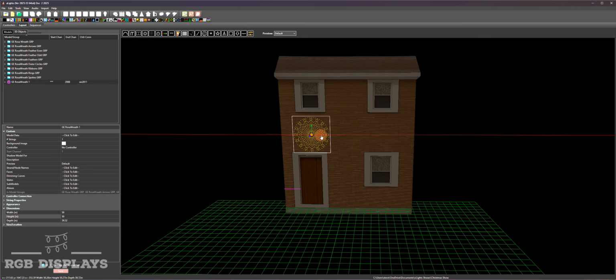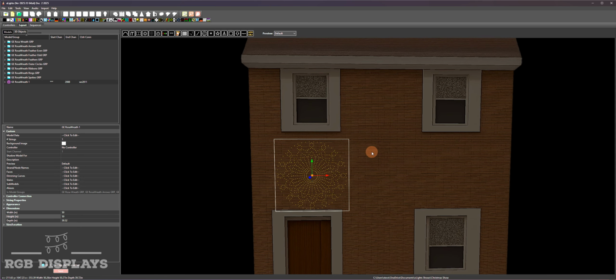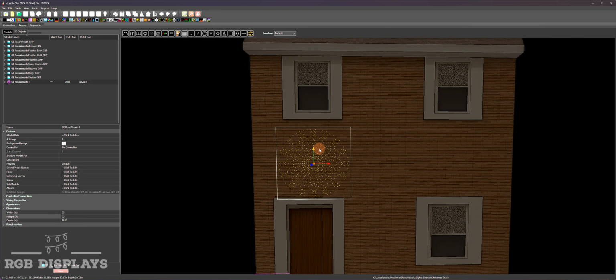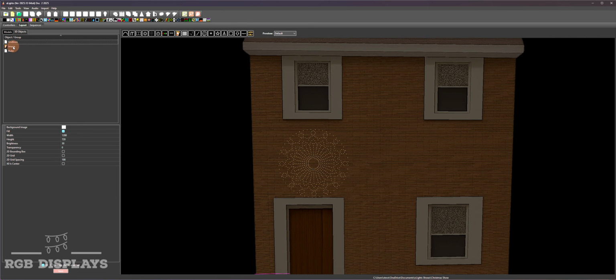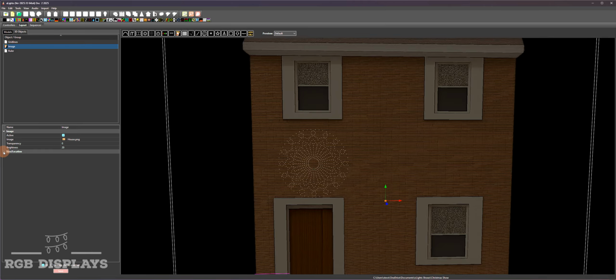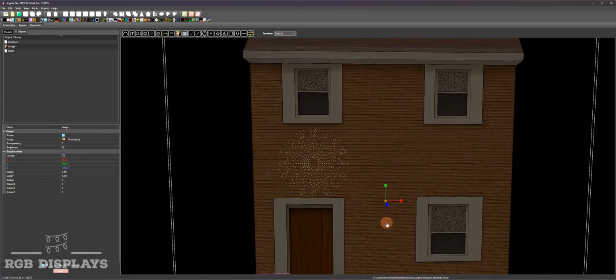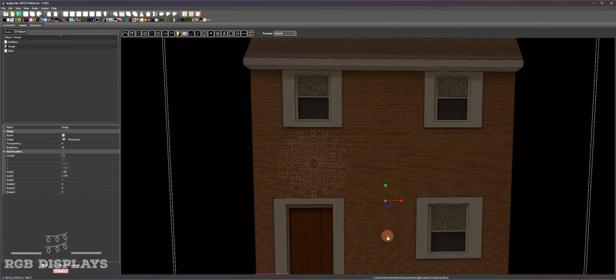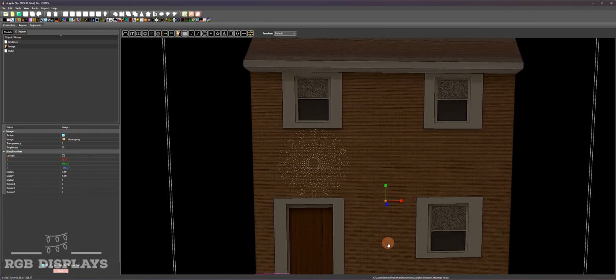Some adjustment to the height will need to be made to the image if we want to have a true scale example. Go to 3D Objects, select Image, and click the red square until you're in Resize mode. In my case, I need to reduce the height, so I move the green square downward. That looks spot on. Final step.